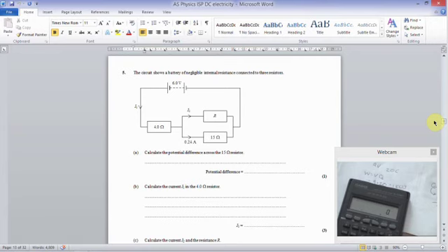So resistance times current, that's 3.6. So what I would do, if you have this in front of you right now, is write your 3.6 down here, but also write it over here right next to this resistor so we know. Now remember, if this is getting 3.6, this must be getting 3.6, okay? And so this whole combination here is getting 3.6, so that must mean 2.4 is going over here.